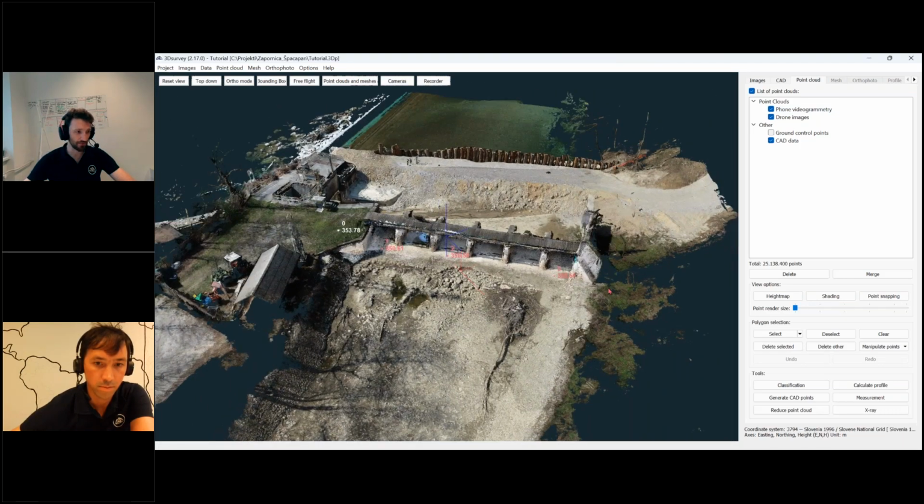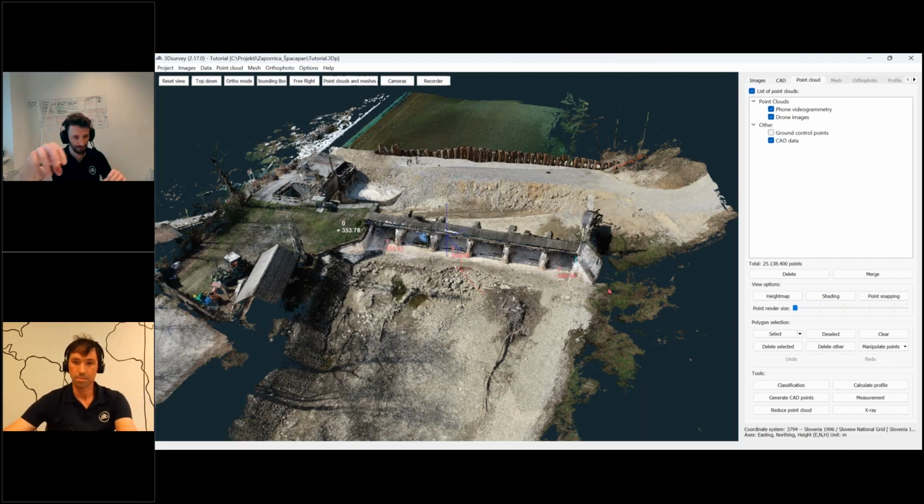You can use it also for different scenarios. For example, if you're using a terrestrial laser scanner and you have multiple standing points and your scans are unorientated, you have to manually match them together. Make sure that every scan catches at least 3 points where you orientate and connect it to the neighboring point cloud.